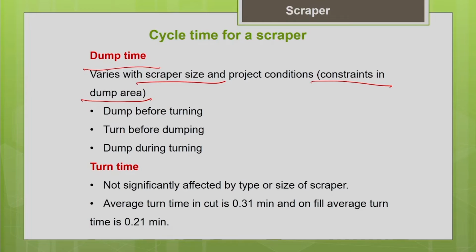Now, we are discussing the dumping time. You can see that there are different ways to dump in a project site, and everything depends upon your project site constraints. Sometimes your scraper will dump before turning. Before turning itself it will dump, and this is a very safe way, because if it turns in a loaded condition, it is not safe for the scraper. So, this is the best way: dump before turning.